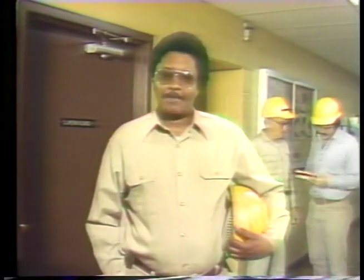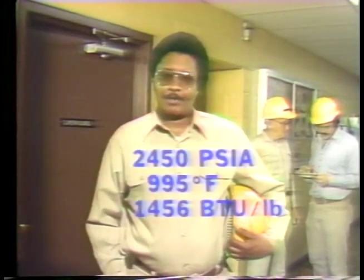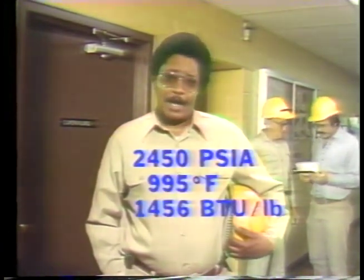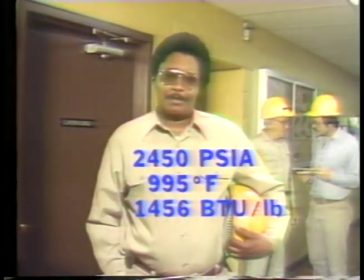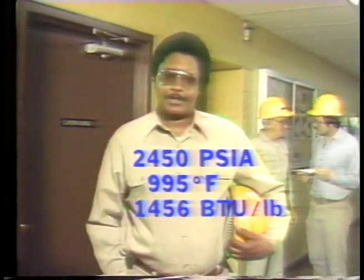By using the steam tables and following a procedure similar to the one we used before, we can calculate the enthalpy at 5 degrees less. We've already done this for you, and at 2,450 psia and 995 degrees Fahrenheit, the enthalpy of the steam is 1,456 BTUs per pound. The difference between these two values is 3.2 BTUs per pound, which is the loss we're concerned with.